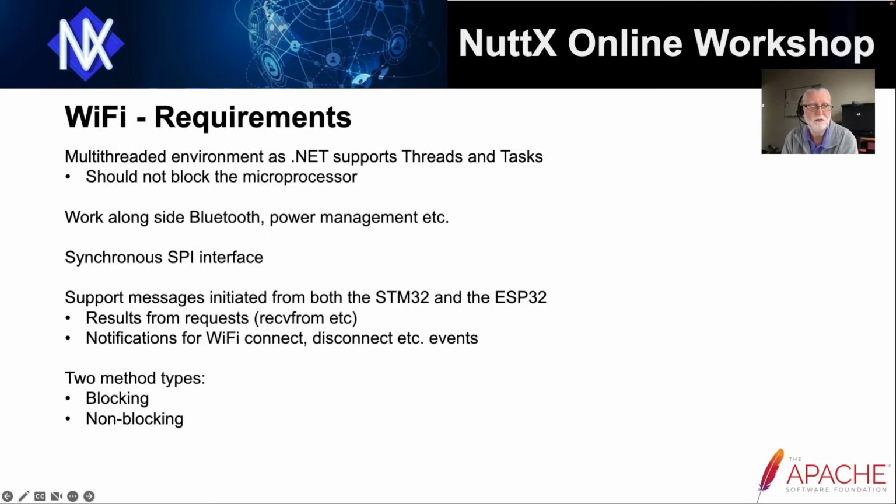And from the STM32 perspective, we provided support for two different types of methods, and we've called those methods blocking and non-blocking. So if you take something like a receive from or a send to POSIX API call, they are blocking messages in that when we generate the message that we send over, or when we generate the request from the platform abstraction layer, Mono itself is expecting to wait until a response is received.